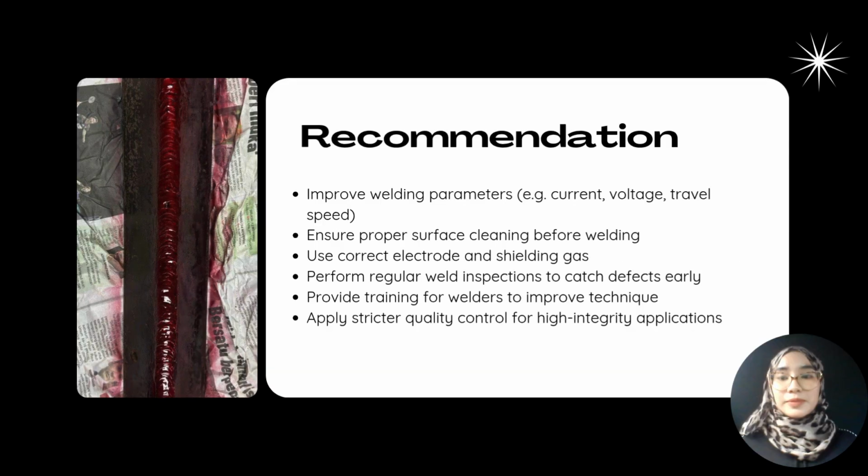These recommendations are based on our inspection results using visual testing and liquid penetrant testing, where we identified a single surface breaking blowhole. Based on the results of our inspection, I would like to recommend several improvements. Firstly, optimizing welding parameters such as current, voltage, and travel speed can help minimize gas entrapment that causes blowholes. Second, proper surface cleaning before welding is essential to prevent contamination that could lead to porosity. Third, it's important to use the correct electrode and shielding gas combination to ensure a stable arc and proper fusion.